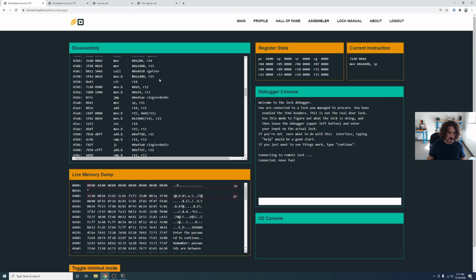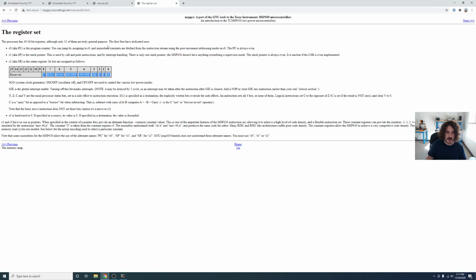So what we're trying to do is add up a whole bunch of numbers that will eventually get FF00 into this register. The problem is that we need to make sure that this bit is never set. Setting the CPU off bit will literally turn the processor off. And so we need to make sure that the numbers we add up never set that bit.